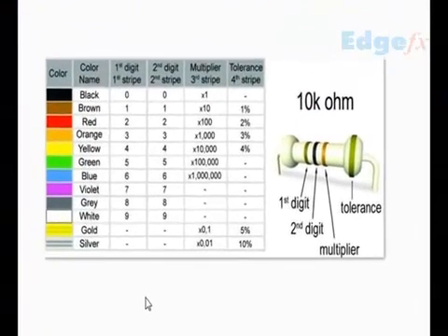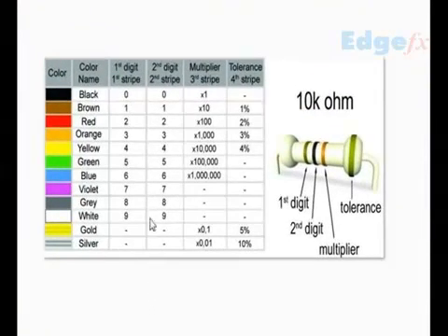An understanding tip here: wherever the end is, we will always read from this side, not from this side. We read from this side, and when the last band is black, we have said the last band is only the number of zeros, so it is 0.